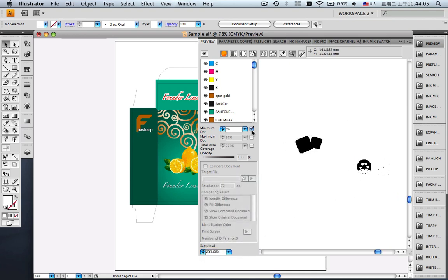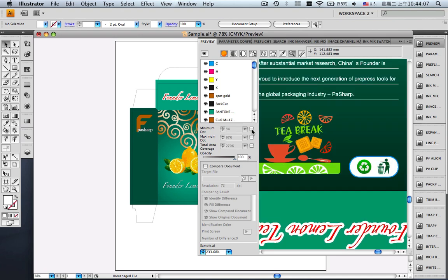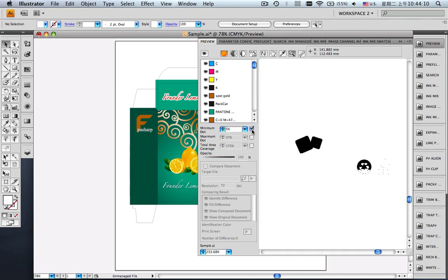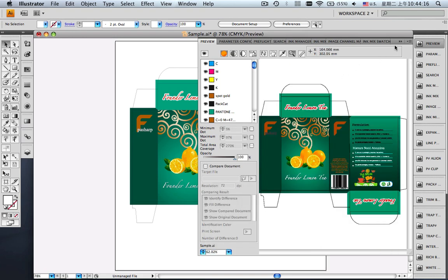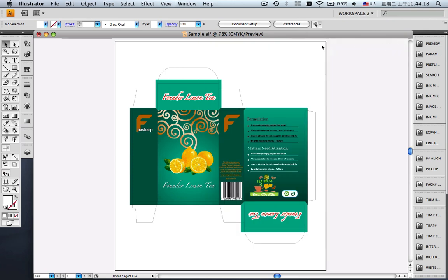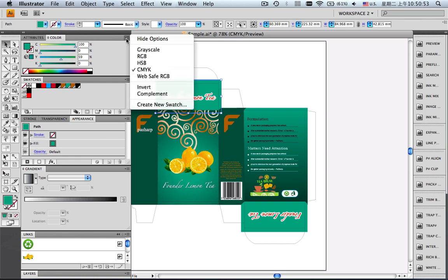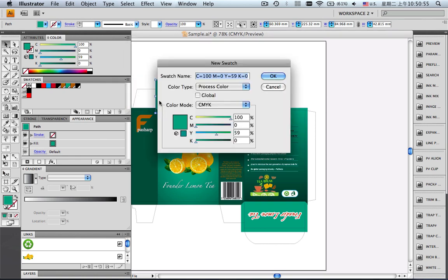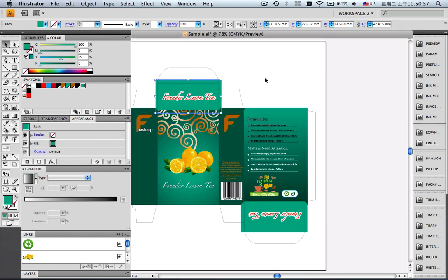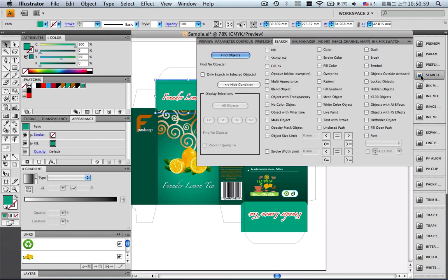You can add a selected ink or color to AI swatches and use it in the search function in order to find objects which also use this color. By adding this color to Search Sharp and then trying to find the objects, after you find them, you can conveniently replace the ink with another one, for example, a spot color or some other inks.